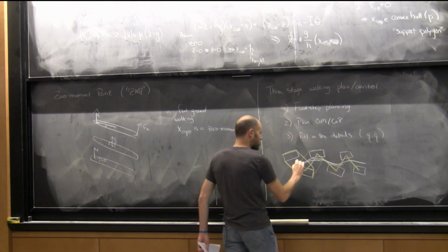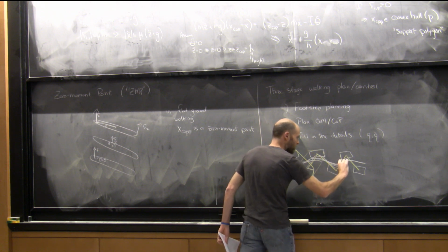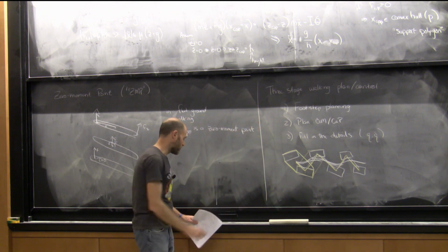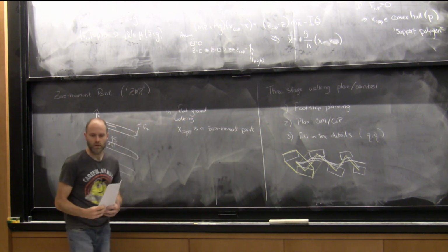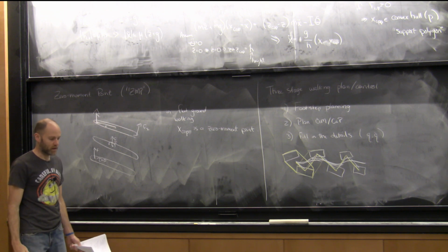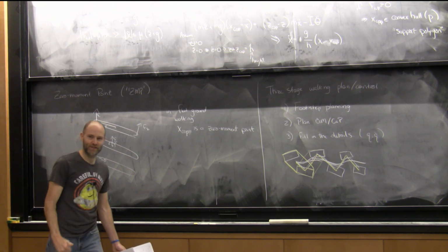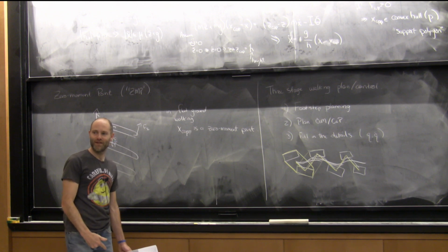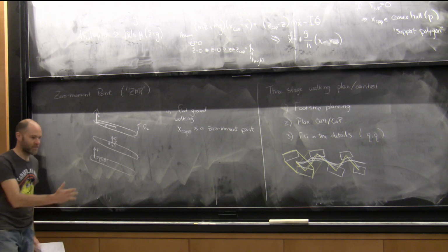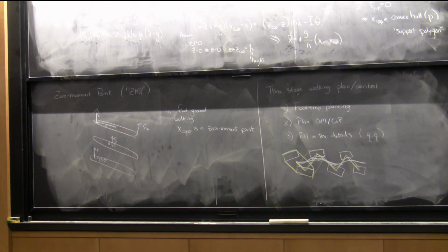So a slow trajectory will follow the ZMP more closely, but a fast trajectory will actually be right more down the middle. That was a really interesting experience for us when we were trying to make the real robot walk. And a lot of people have this experience, I think, that actually walking slowly is harder because you have to get your center of mass really over your foot, and you're going back and forth. Once you start walking faster, your center of mass actually doesn't go side to side very much, and it's easier to walk.